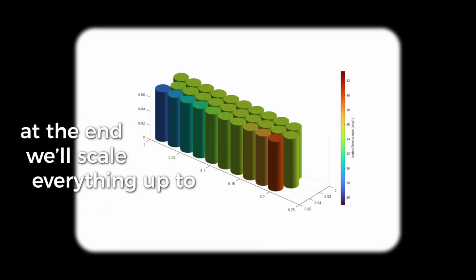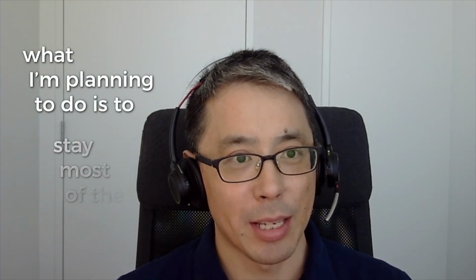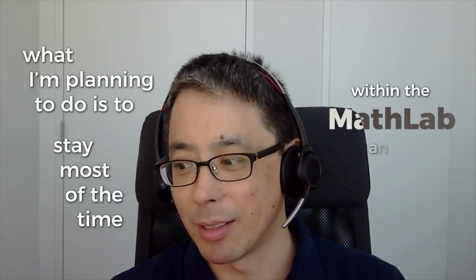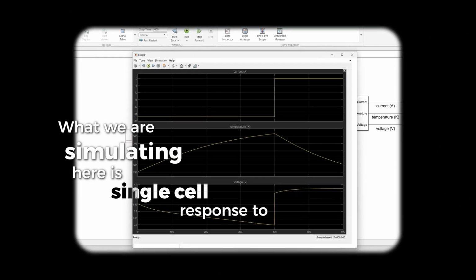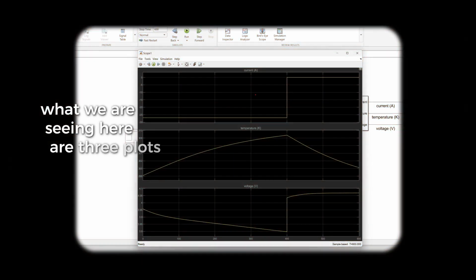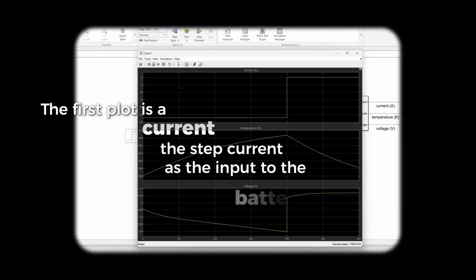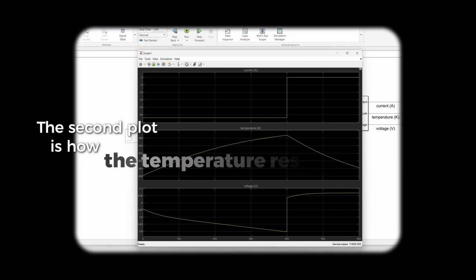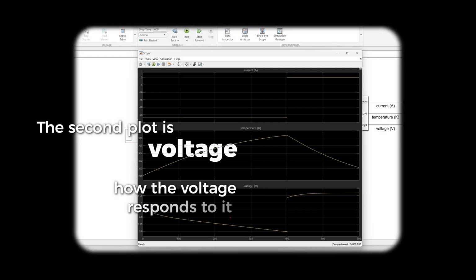Start from battery cells, and then at the end, we'll scale everything up to battery packs. What I'm planning to do is to stay most of the time within the MATLAB and Simulink environment. What we are simulating here is single cell response to step current. What we are seeing here are three plots. The first plot is the current, the step current as the input to the battery cell. The second plot is how the temperature responds to that step current. The third plot is the voltage, how the voltage responds to it.